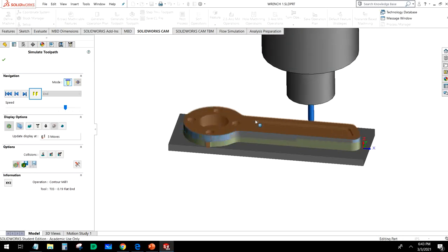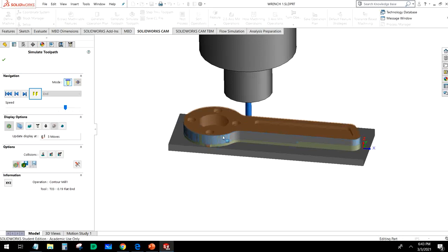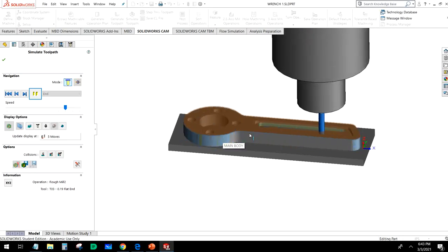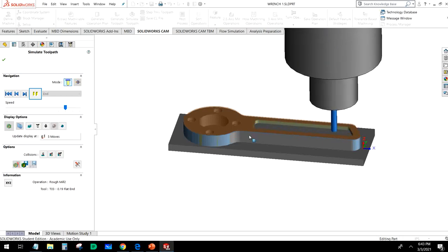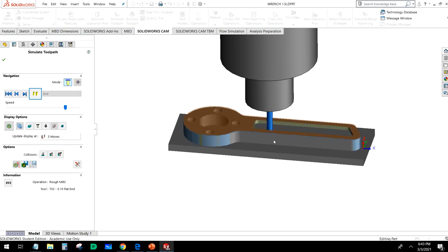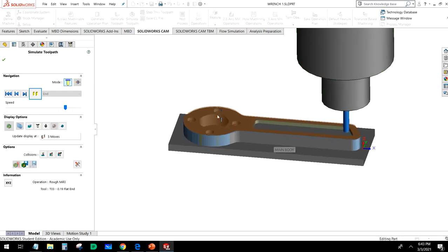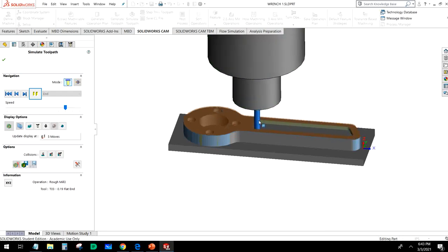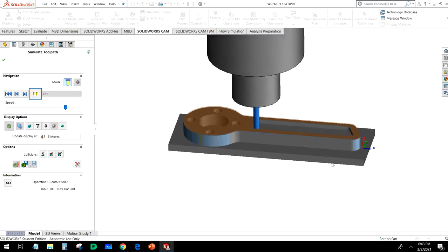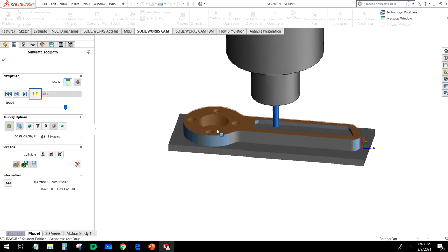And again, it switches to an even smaller end mill. I believe it swaps out to the 3/16 end mill. There's no need to do this, so we're going to make that a 1/2 inch end mill as well. It's going to clean out this center pocket, and then it's going to clean out these corners, do a finish pass in here, then it's going to address these holes.